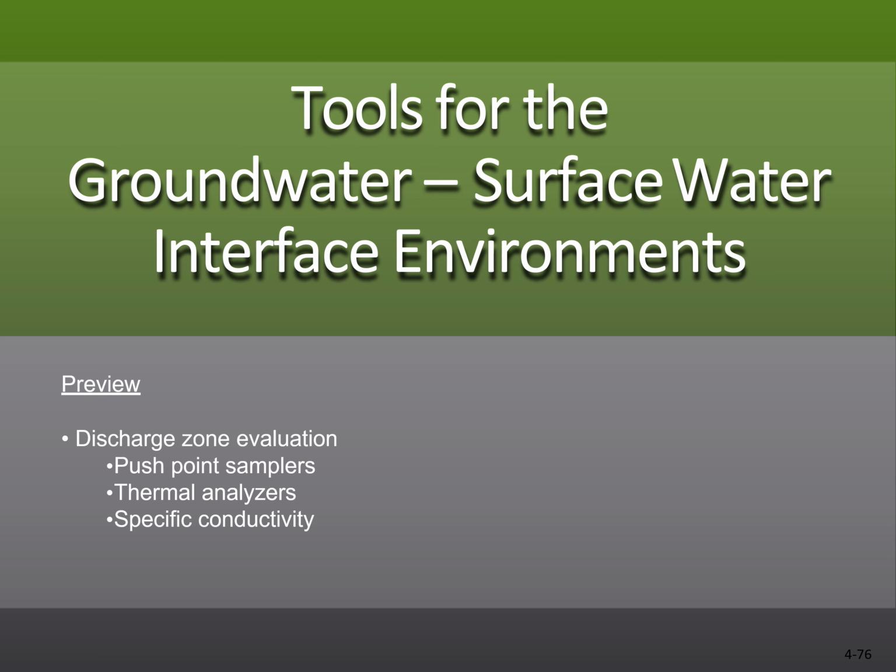So for groundwater surface water zones, one of the things I've learned in the last 10 years or so is that all the groundwater usually goes to a discharge to a creek someplace or to a big river. So understanding this transition from the groundwater to the surface water is becoming an avenue where it sort of expands your hydrogeology notion. And it's useful for both screening, and you can get very detailed levels of understanding because you can work on really short intervals for your sampling.